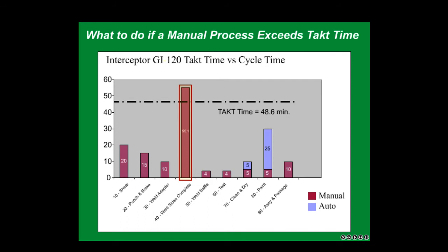If you have a manual task that can be split into smaller pieces, consider having multiple operators work on the part simultaneously. If 2 or more operators can work simultaneously on the same part, or can process half the part and pass it to the second operator, consider having multiple operators work the part. This will result in breaking the operation into 2 parts and bringing each bar below takt time, thus breaking our constraint. In our case, we added a second welder and a piece of WIP so that one operator can work on a part and pass it to the other welder.